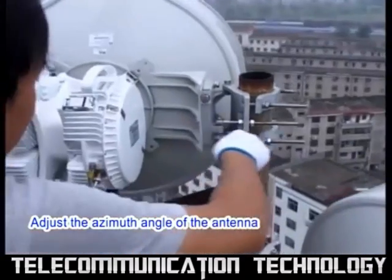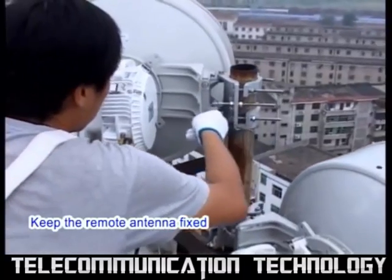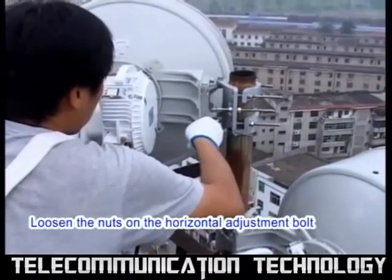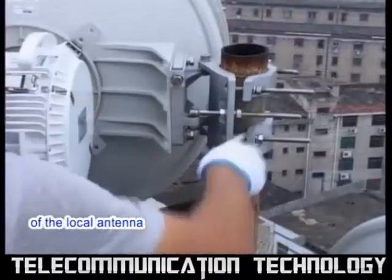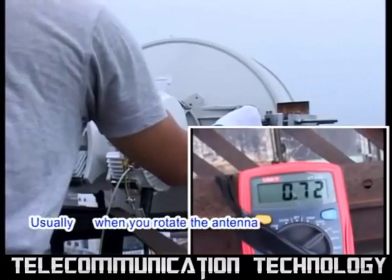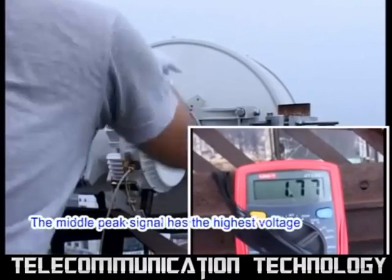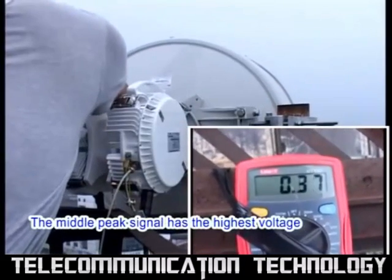2. Adjust the azimuth angle of the antenna. Keep the remote antenna fixed. Loosen the nuts on the horizontal adjustment bolt of the local antenna. Rotate the antenna around the pole. Usually, when you rotate the antenna, 3 peak signals can be obtained. The middle peak signal has the highest voltage.